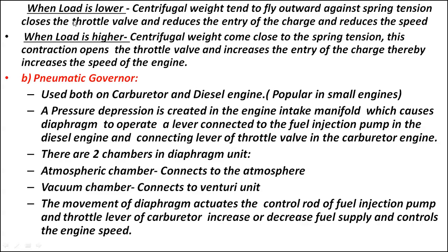Here is how the principle works. When the load is reduced, the centrifugal weights tend to fly in the outward direction against the spring tension, so that the entry of charge is reduced. When the entry of charge is reduced, the speed of the engine also reduces.